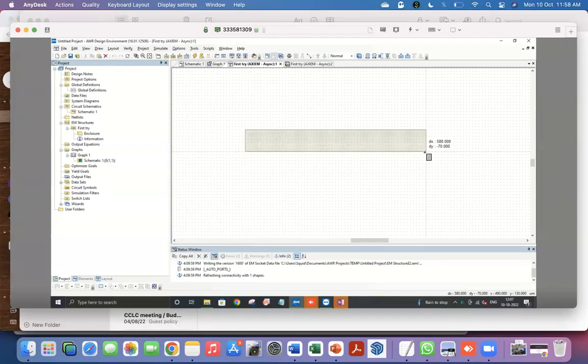So one little trick is that while you're drawing it, you can press the space bar and it gives this pop-up window so that you can actually enter the number. So if I remember correctly, we needed something close to 1,000 micron wide for getting something close to 50 ohms. So let me put, so dy has to be big, and the length I will put like some 5,000.